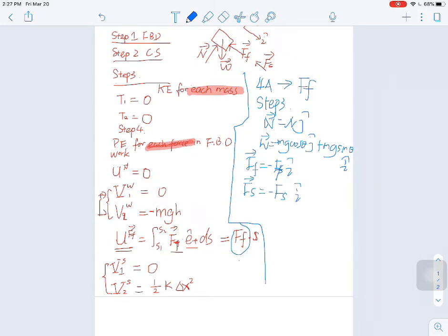And then step 4 is to write all the accelerations. The acceleration of this block, right? a equals a, which is only in the i direction. Oops, that's i hat. And step 5 for 4a is to apply F equals ma and extract the scalar equations.